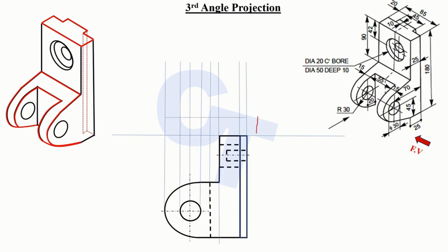And now it's time to draw a plan. So from our plan, as you can see, this is what we have. I've indicated it in red. That means we're going to be looking at the top view. Okay, so plane number 1 and plane number 2. How do we know the orientation? We said that to see the orientation from the front view. So we're going to start with plane number 1.